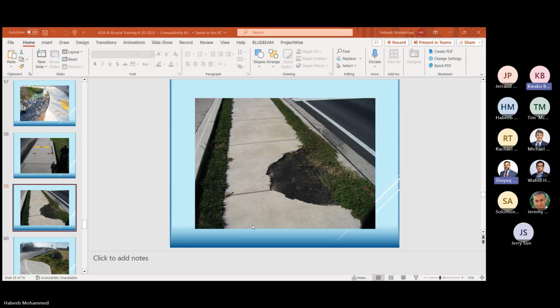Yeah, you need a buffer. If they have to absolutely meet the ADA criteria for the sidewalk, they will realign away from the roadway. That way they can have separation from the roadway and probably have some kind of wall structure. That way, the sidewalk can be a different grade compared to the roadway grade.